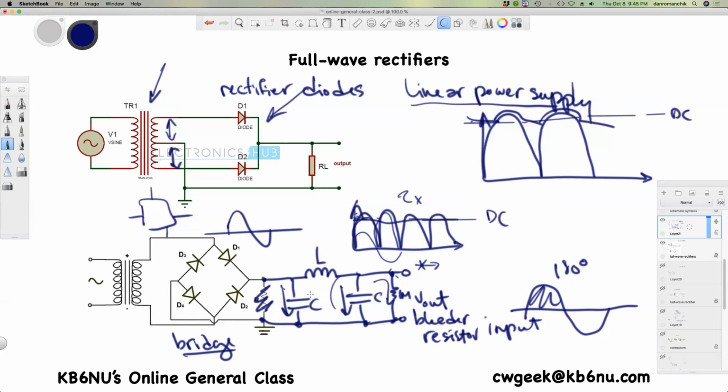Hey, Dan? Yeah. One of the reasons they're going to the switching supplies is the switching supplies create a square wave instead of a sine wave. Well, yeah, kind of. I mean, they're switching the AC instead of transforming the AC, and that allows them, like I say, to use smaller components and therefore be lighter, and actually they're more efficient too.